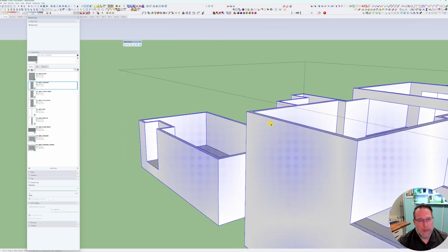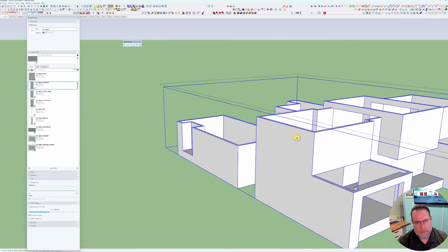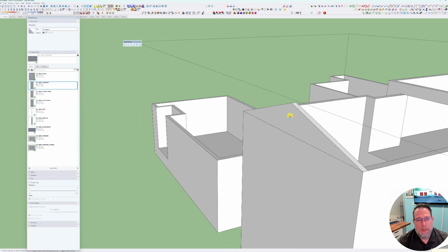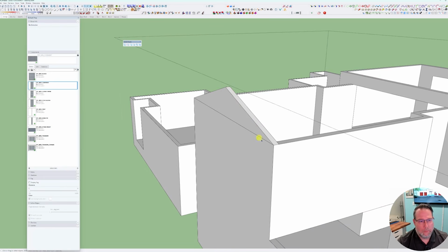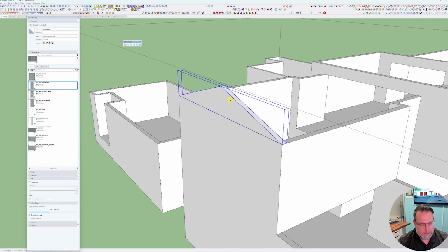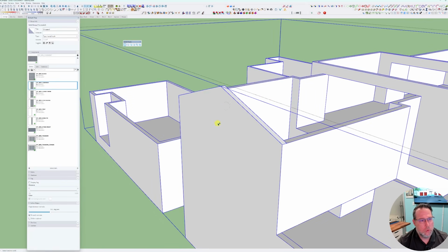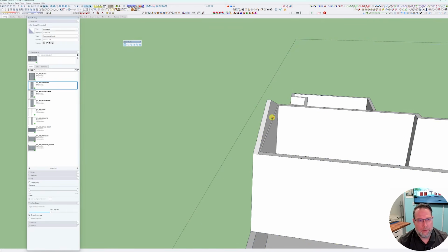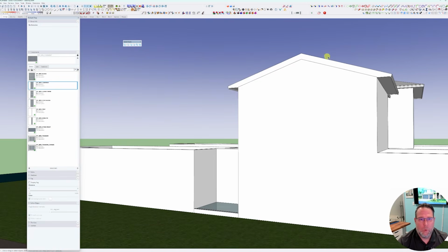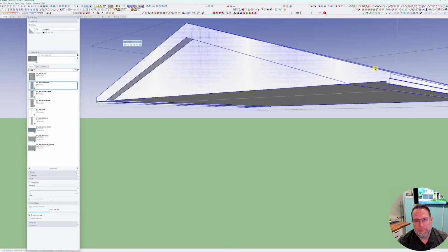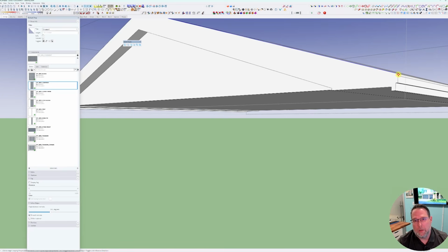and then I want to come back to my walls, turn that into a group, paste in place, and then push-pull 8 inches, because this is now going to be my rake beam, and turn that into a group. And since these are now both solids, we can join these together, and we now have a perfect wall for our gable. So then we can start playing with how this would all really start coming out.